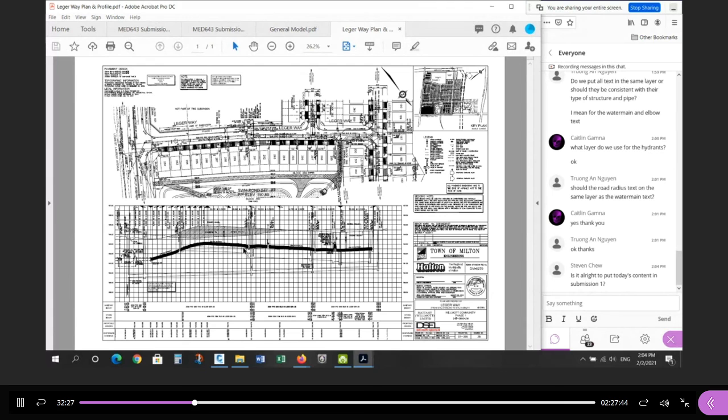Okay, so I want to recreate Ledgerway. I'd like to create ultimately the corridor for this road. Okay, so to create the corridor for the road, I need the 3 basic building blocks. I need the horizontal alignment, I need the vertical alignment, and I need the cross section. Okay, I need those 3 parts: plan, profile, cross section, horizontal alignment, vertical alignment, and assembly with subassembly parts for Ledgerway, so that I create a surface of the proposed design for Ledgerway.